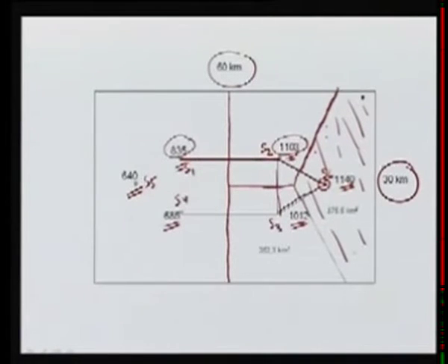So this effective area of the gauge S6 can be plotted and measured, and the area comes out to be 375.5 square kilometers. Similarly, for the gauge S3, any point in this area will be closer to S3 than any other gauge, and this area turns out to be 262.3 square kilometers. Since it's symmetric, S2 will also have the same area, S4 and S1 will also have the same area, and S5 will have the same area as S6.